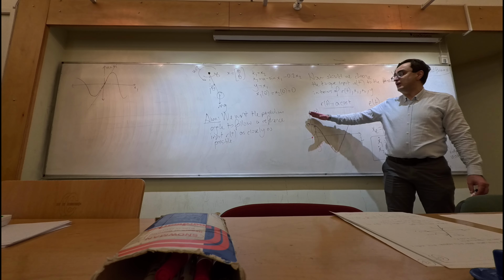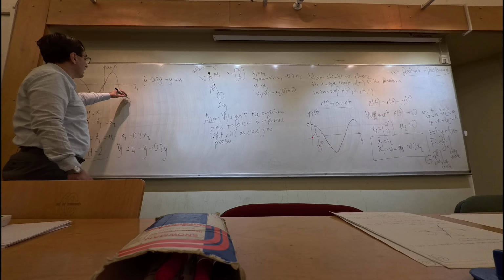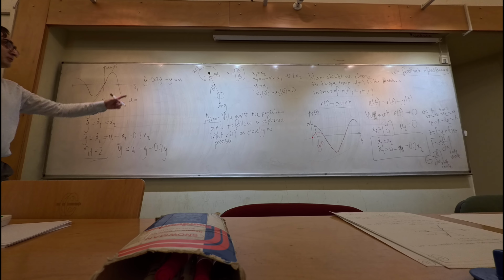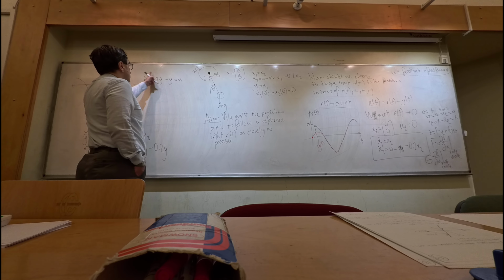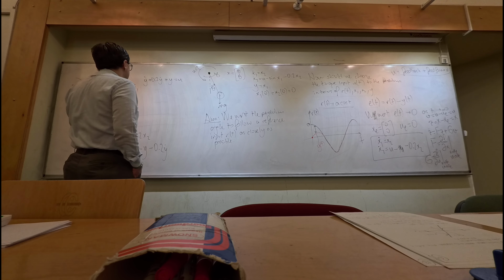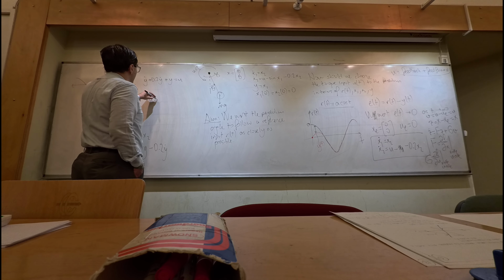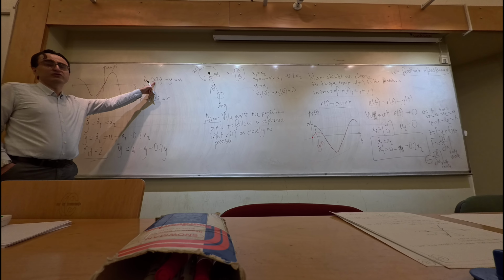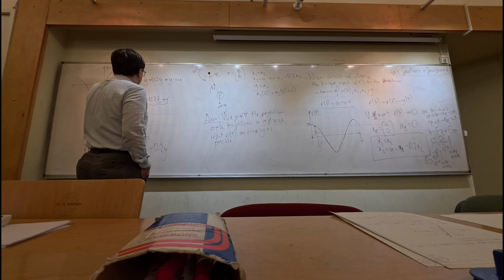Then what we're going to do is start choosing this u. That is going to be the controller equation. I will choose u in the following way. The input u is going to be formed out of two components. The first component is the feed-forward part, and the second component is the feedback error part. The first part is related to the feed-forward controller, and this is going to be r double dot plus 0.2 r dot plus r. So we are going to replicate the left-hand side of this equation in terms of the signal r, and this part forms the feed-forward part of the input.